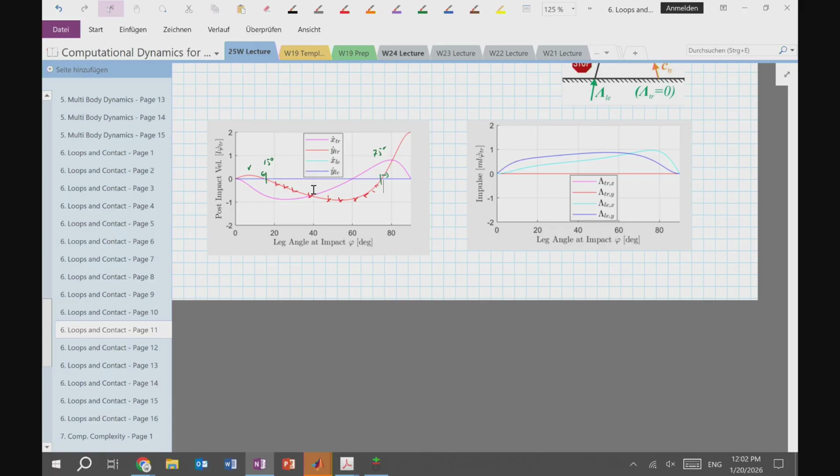Right? This is basically my definition of coefficient of friction of infinity, these spikes. But if I pull here, what will happen? Now I look at this as a dynamical system. If I pull here, what will happen is that this guy will move up. And at some point, because I have this angle, the trick here is to have an angle, this thing will jump over these little spikes and then will continue to move. And so this is sort of the macroscopic or microscopic view of this idea of sliding